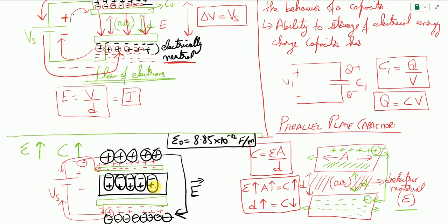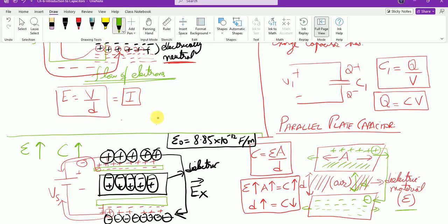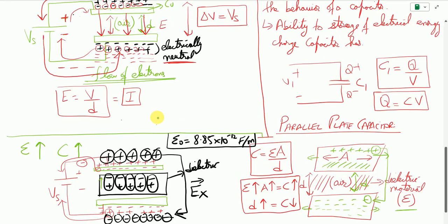In this way you can see the dielectric material is trying to resist the formation of this electric field, because an internal electric field is made inside the dielectric material, which we can see from here. The original field is moving from here to here, but inside the material another electric field opposite to the original electric field is made, which is opposing the original field. This means that the current is having difficulty being generated, or the displacement current is having difficulty being generated.